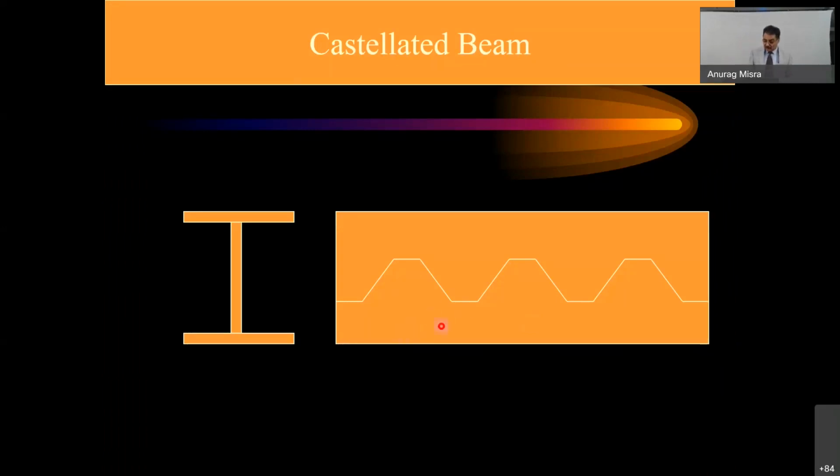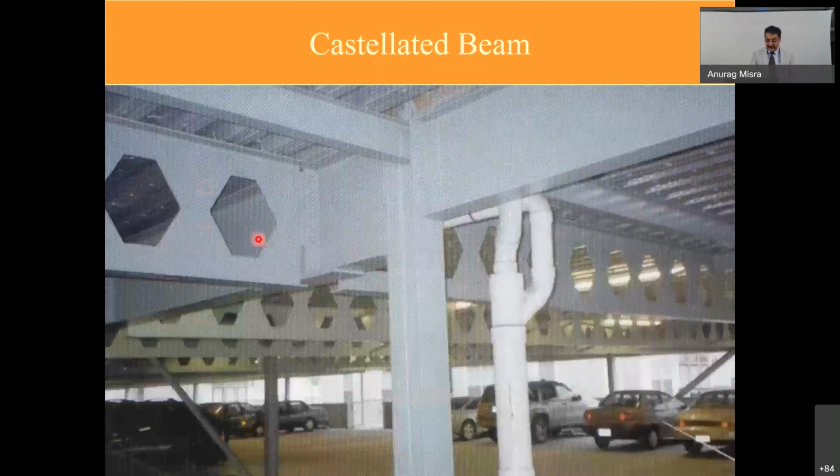Then we also quickly look at the castellated beams where we have to economize. So if you are going for an I-beam with this plate like this, having certain moment carrying capacity, and if you cut it like this, and just this place goes here and this place goes here, so you get a hole like that. So you have to just check the shear connections,